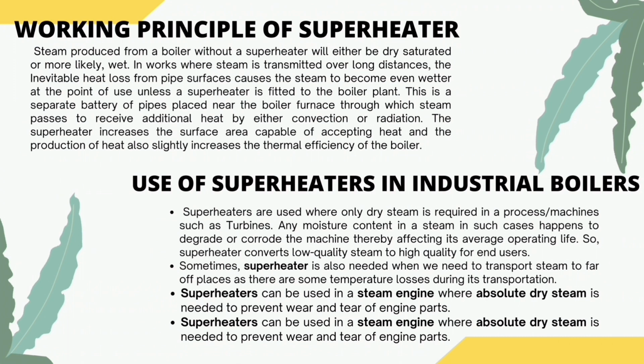Next, superheater is also needed when we need to transport steam to far off place, as there is some temperature loss during its transportation. So the third, superheater can be used in steam engine where absolutely dry steam is needed to prevent wear and tear of engine parts.